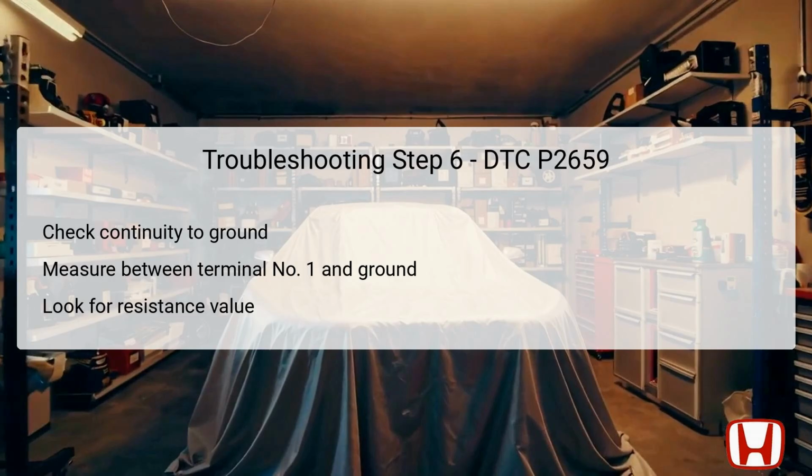If resistance is noted at the body ground, it raises concerns regarding the circuit integrity or potential issues in the solenoid. This step is paramount as grounding issues can lead to erratic performance in electronic devices. Comprehensive testing in this regard allows mechanics to isolate potential electrical failures and take corrective actions, ensuring reliable operation of the rocker arm oil control system.